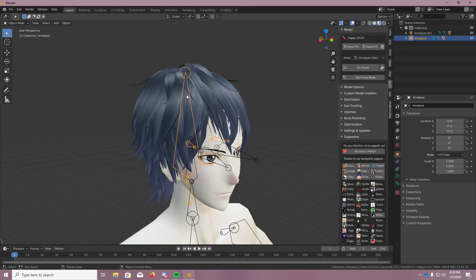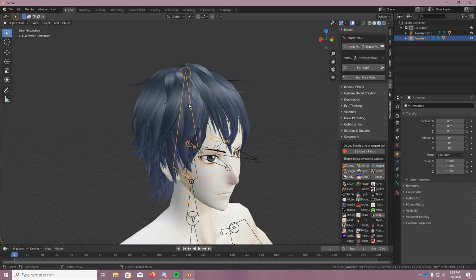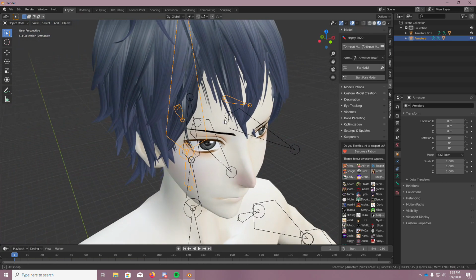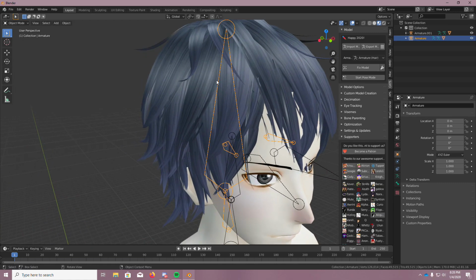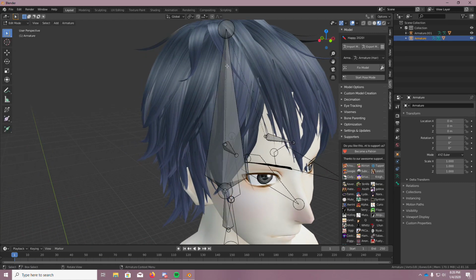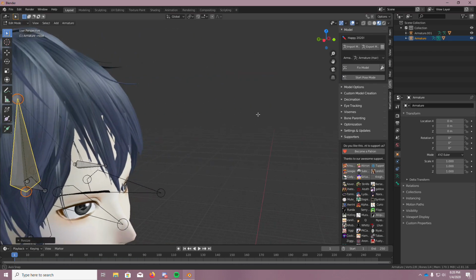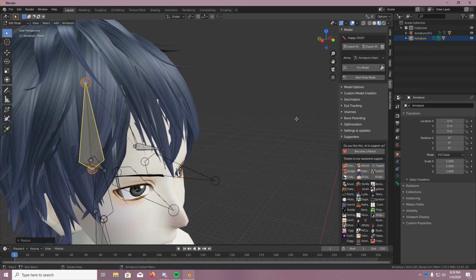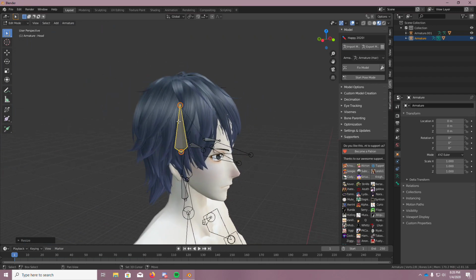So that's very clearly the head bone, those are the eyes. So now what we should do is scale the armature down, or scale the actual bone so that it lines up with the eyes so they can merge. So we're gonna go to edit mode. Let's scale this down a bit, like that. To do that, you have to press the S button to scale up or down, and then you move the mouse up and down to scale appropriately.